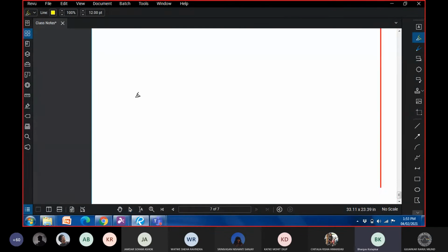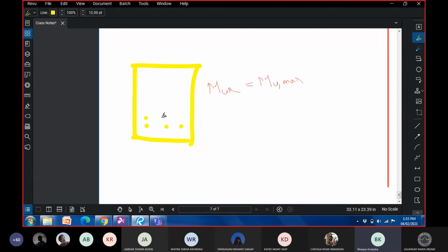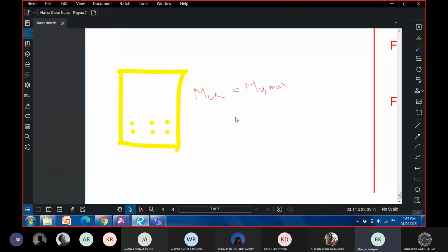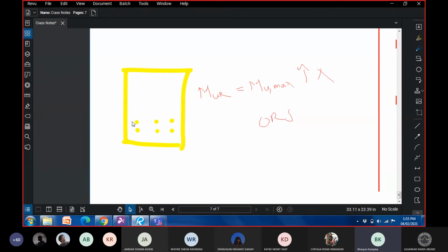So just to summarize what we just wrote down, a singly reinforced section has an upper limit for MUR, and this MUR is equal to Mu max. Now if we increase the amount of reinforcement here, we can attain a value greater than Mu max, but it is not permitted because in that case our section will be an over reinforced section. So let's say that we have already exhausted all our capacity and we don't have an option of adding reinforcement on the tension side.